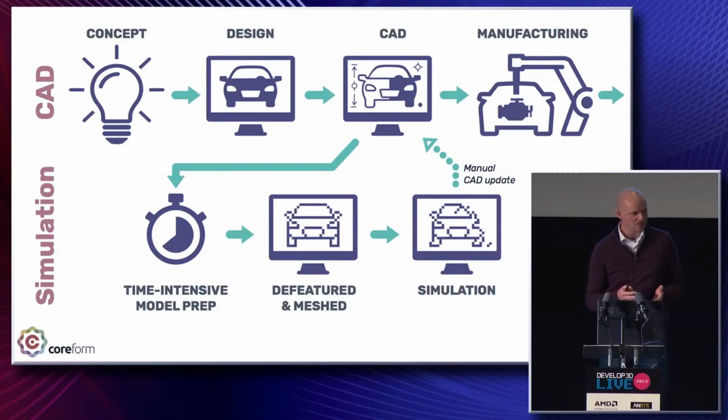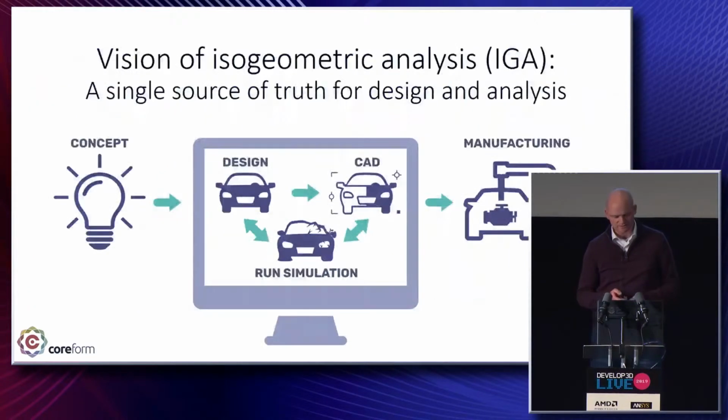And then it doesn't make much sense to run these algorithms such as contact and crash that are highly sensitive to the geometric accuracy on a less accurate mesh model. So the only recourse that these companies have is to make very detailed mesh models, which increases computation time and makes these simulations the most expensive jobs run on the HPC units in these companies. So maybe you're an analyst who's lucky enough to work on simple problems that can be generated by automated meshing, but for hard problems, these issues persist across industries.